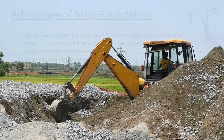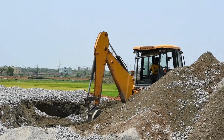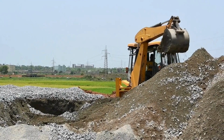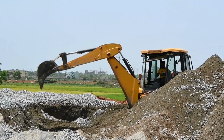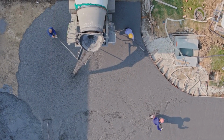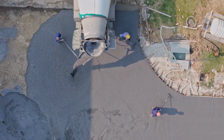Now let's briefly see how a strip foundation is constructed. The process begins by setting out the building and excavating a continuous trench to the required width and depth specified in the structural drawings. After excavation, the bottom of the trench is leveled and compacted. A layer of lean concrete, also known as blinding concrete, is then placed. This creates a clean, level working surface, protects the reinforcement from soil contamination, and helps maintain the required concrete cover.